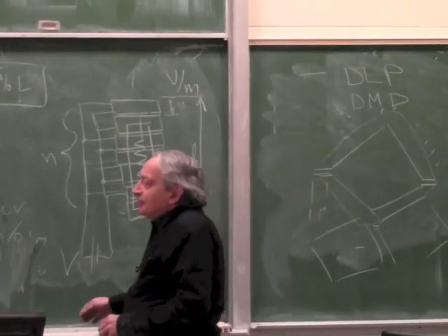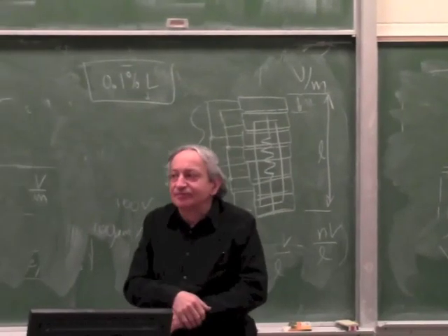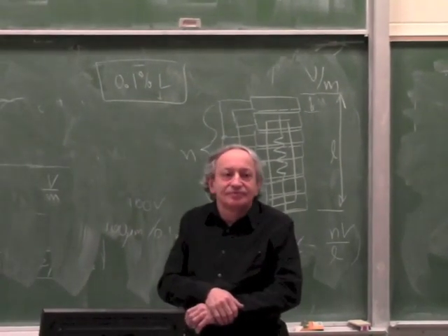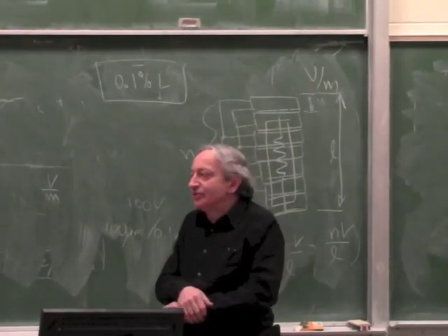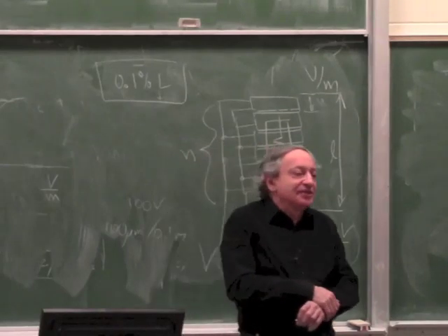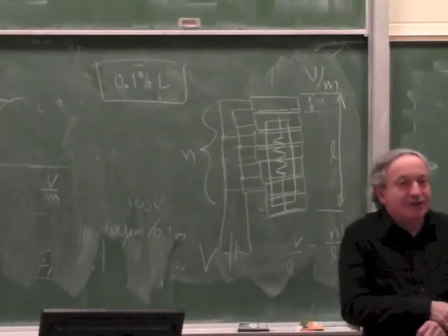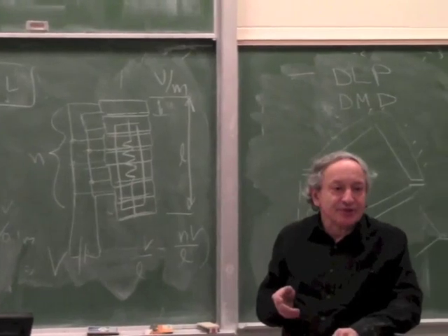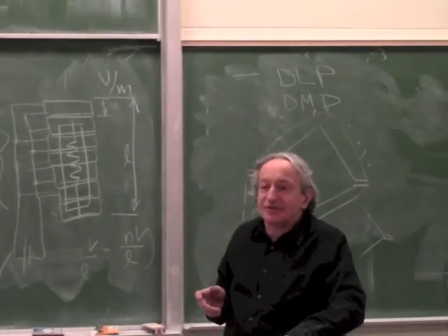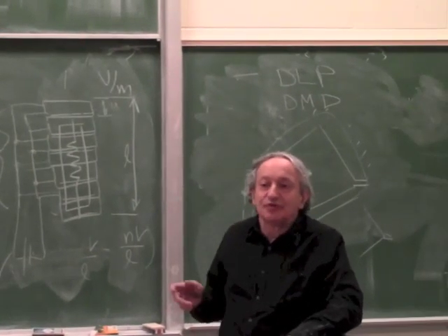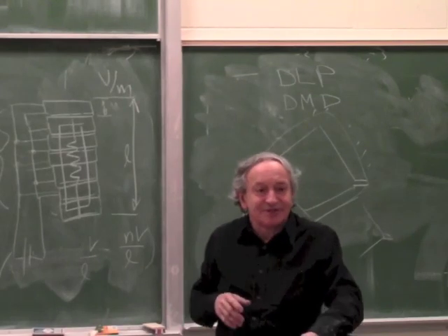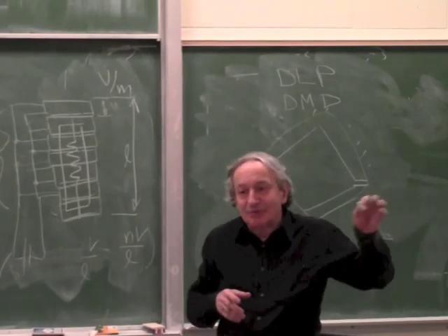So, any questions about piezo actuators? Good. Now, there are many other types of actuators, like I mentioned before, hydraulic actuators. Hydraulic actuators are very good because you can make huge forces in small spaces, because the pump can be somewhere else.